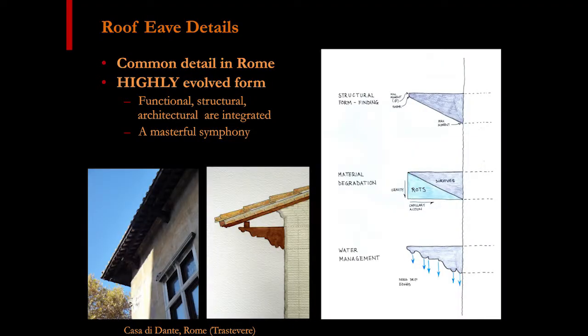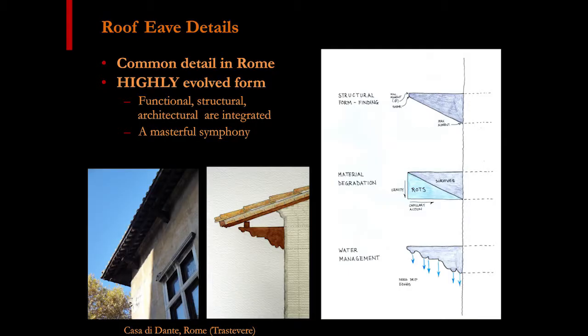And then you might think, well, you could just cut it off at that straight angle. Why do you need all these little ornamental doodads? Isn't that just ornament? Well, those are beautiful, but they're not just strictly ornamental, because when this does get wet, what you really want to do is shed that water as quickly as you can. So those create a whole series of drips to get that water off. And I'd also want to point out that when you look at this beautiful element, the rafter overhangs it. The stop, which keeps the decking from sliding off, overhangs that, and then the clay tile overhangs that. So everything overhangs everything else. So as water comes down off this roof, it's not curling back around here and getting this wet. It's clearing it straight off.